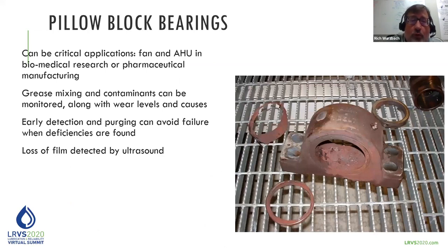Pillar block bearings, another application. Sometimes these can be very critical. One of the first applications, or challenges, that we used as the motivation to develop these samplers was in the National Institutes of Health, looking at air handler unit fans. We were able to identify grease mixing in some cases, the presence of contaminants along with wear levels, and maybe as a complement to, say, vibration analysis or mechanical ultrasound condition determination,